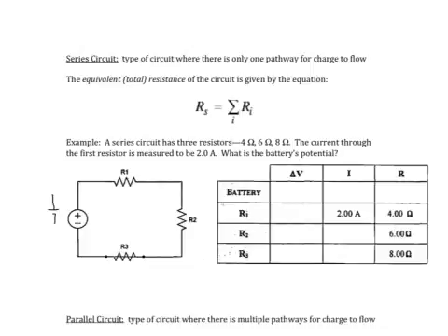So in this little diagram here, we can see that there's a battery. Now it's labeled with a positive and negative, but I actually went ahead and drew a picture here on the side of what the schematic for a battery might look like. So, for example, charge would flow from the positive terminal. So current flows through the positive, goes through R1, resistor 1, goes through resistor 2, goes through resistor 3, and back into the terminal. So this is an example of a series circuit, where there's one pathway for charge to flow.